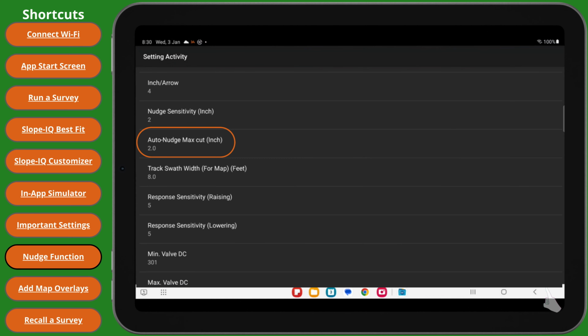You can also adjust the setting for Auto Nudge Maximum Cut. This is the maximum depth per pass that your implement can comfortably handle. For example, a value of 2 inches means that on the first pass, your depth will never be deeper than 2 inches. On the second pass, the depth will be a maximum of 4 inches, and so on until the final grade is achieved.